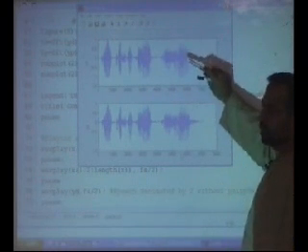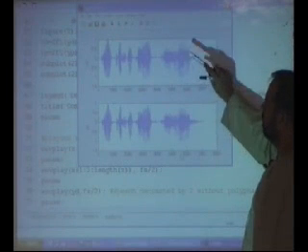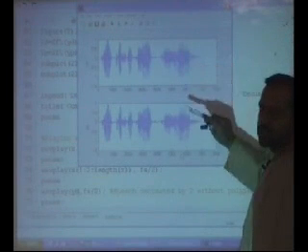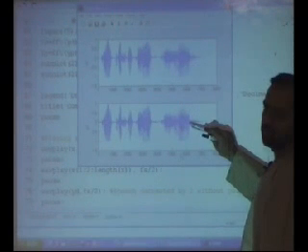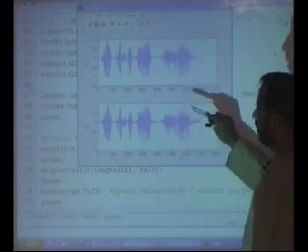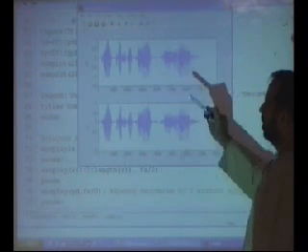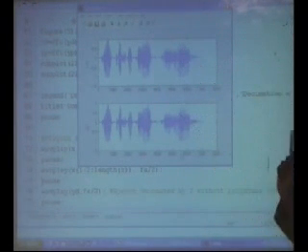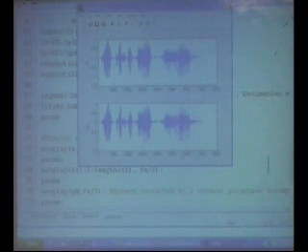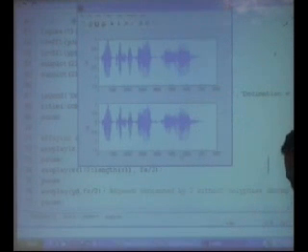This is where you pass it through the filter, then throw away samples. This is where you never throw away any sample. By polyphase decomposition, you take care of throwing away samples. Both are the same signals, so you just do better than this. And this is the decimation version. Same.